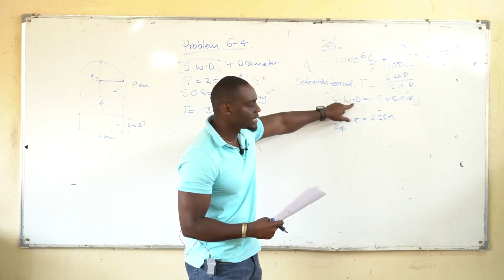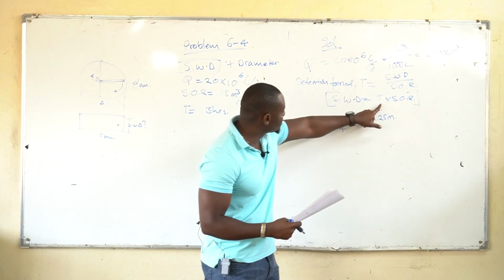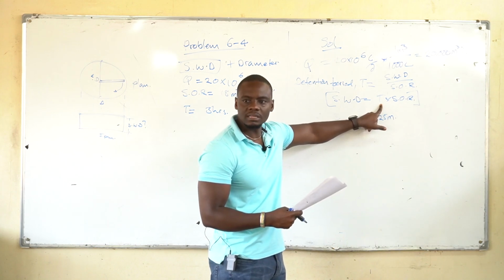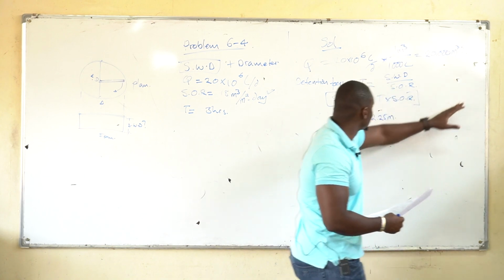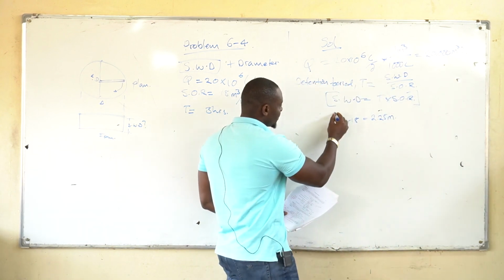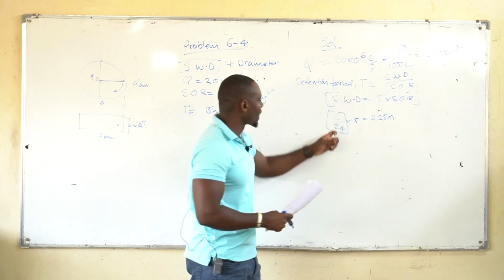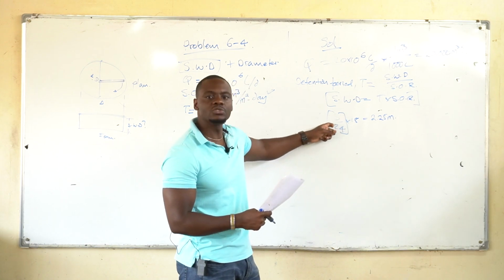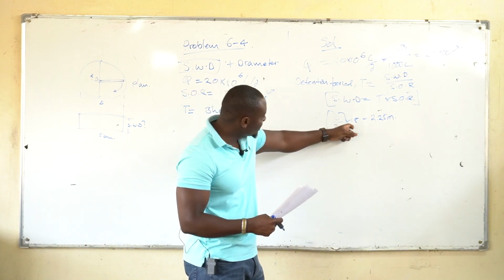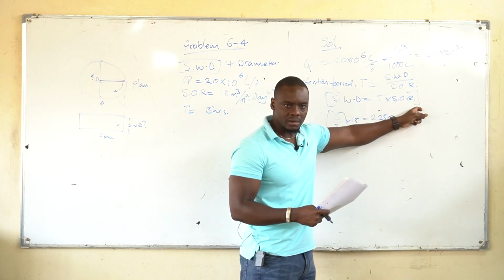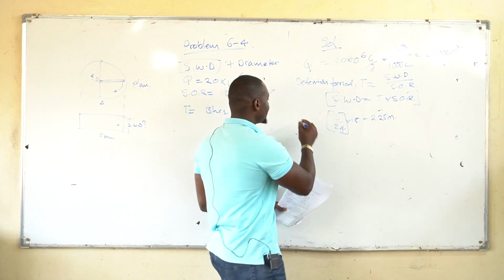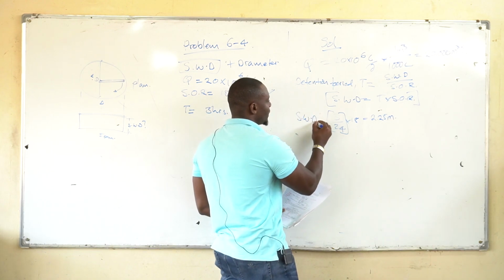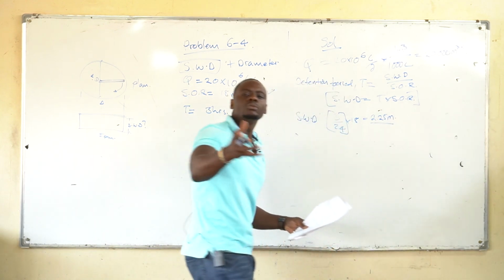We made this the subject, time. And the time, since we can't work with it in hours, why? Because we've already begun working everything in days. So we're converting our 3 hours into what? Into days. This is just the fastest way to convert it into days. Then we are multiplying this by the SOR, which is the velocity, which is 18. So what you have there is your first answer, your side water depth.